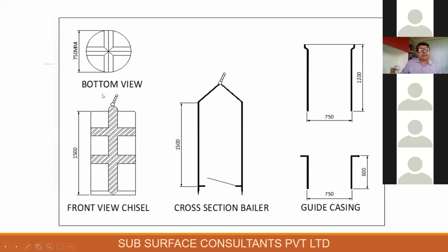If you are working with this, you will find that this face is very critical, because this is the one which is going to hit the rock, hit the surface, and cut through the rock. So this portion has to be coated with the hard facing material, which will last longer. Otherwise, these are MS blades, and the MS blades may crack after some time. To prevent that cracking, these have to be completely coated with the hard facing material.